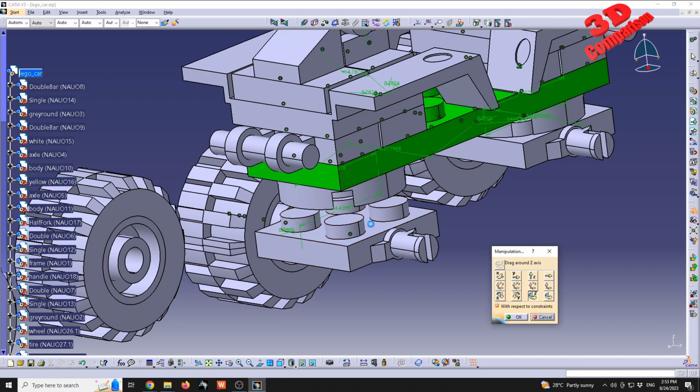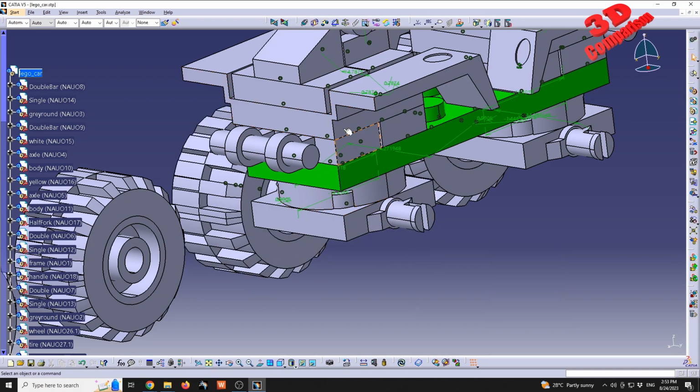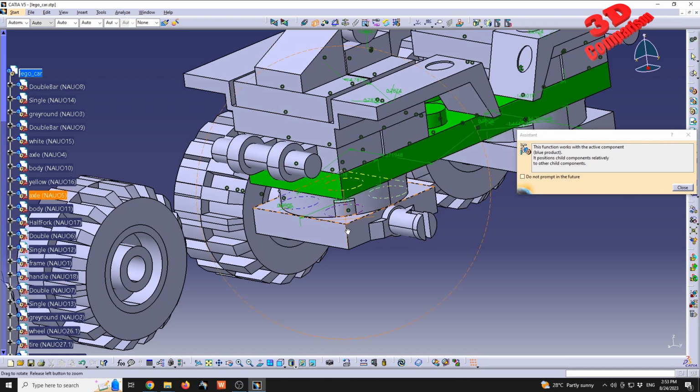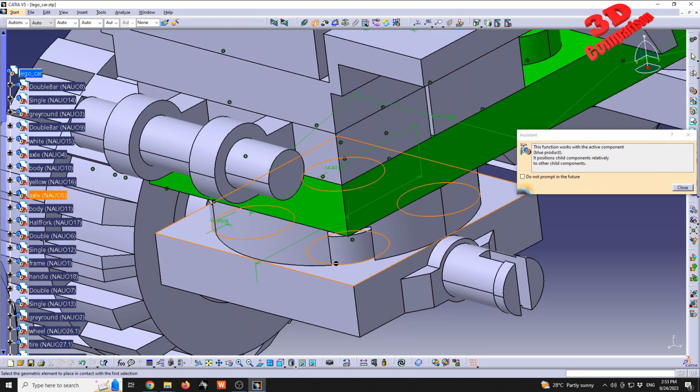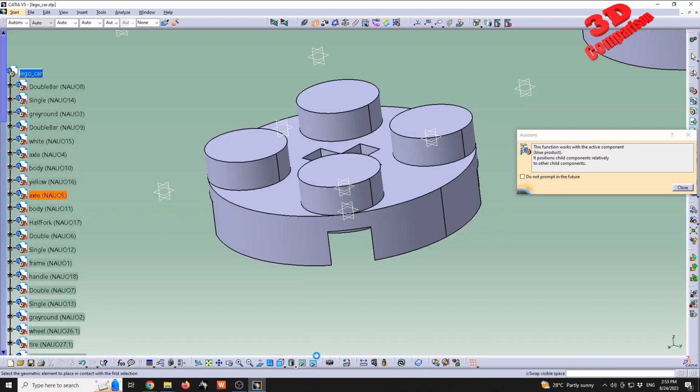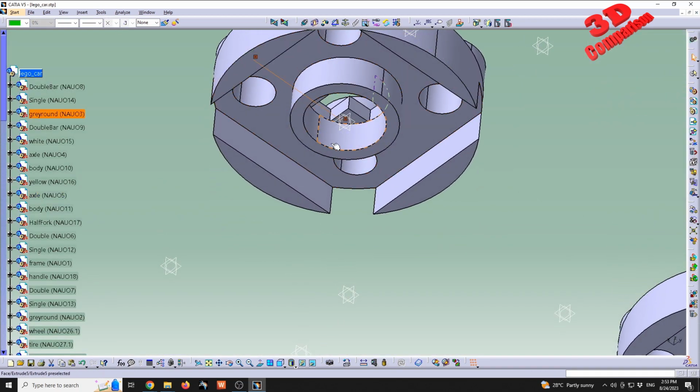So we're just gonna define that collision plane. And just as I said before, this contact constraint and coincident constraint will act the same. So I can go with contact constraint between the top part, and if I'm gonna hide and show, that one will be with the bottom.